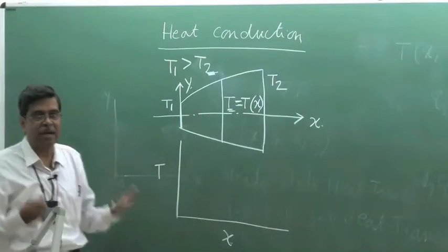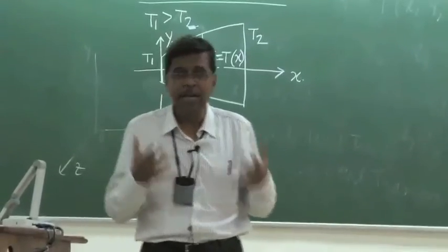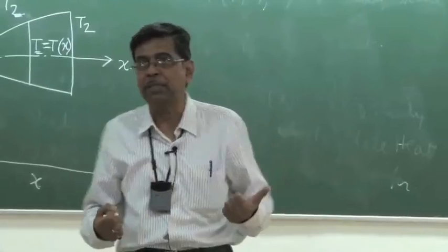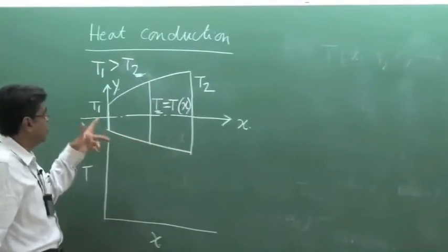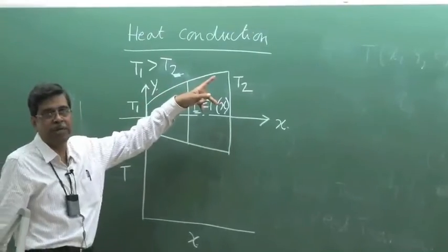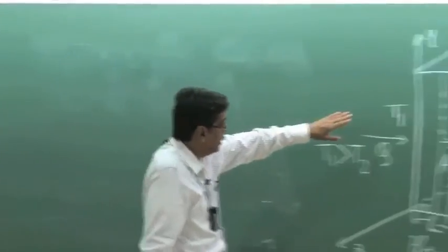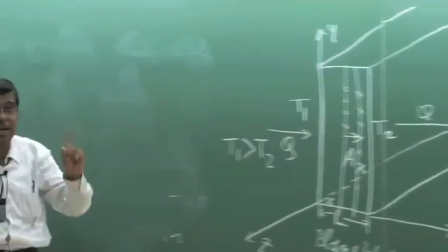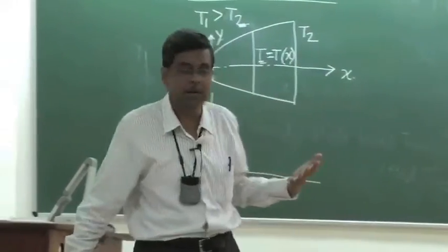That means it is, in other words, visualization of really, truly speaking, two-dimensional heat conduction as one-dimensional, when the variation in the other direction is small. So, this happens in this type of geometry. Purely, strictly speaking, one-dimensional heat conduction happens in a plane area flow. This I will connect afterwards after the derivation of the general heat conduction equation.